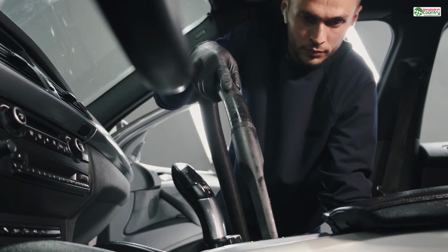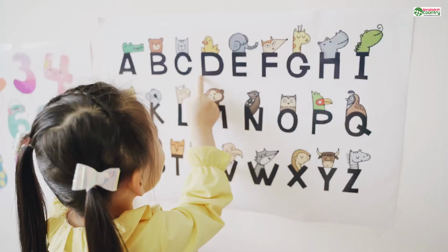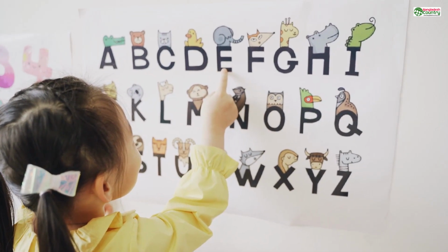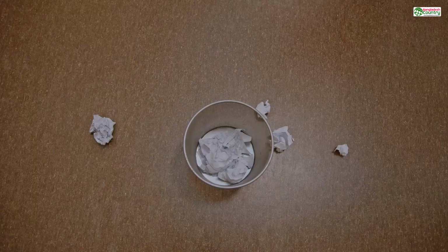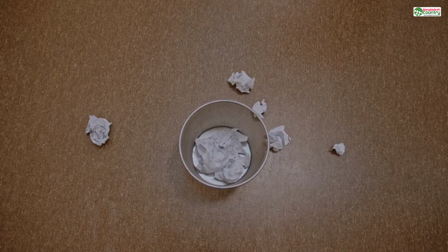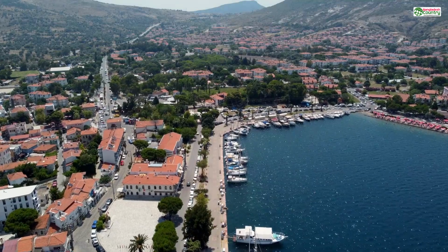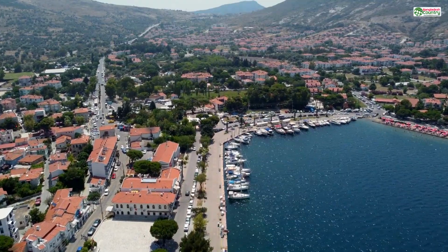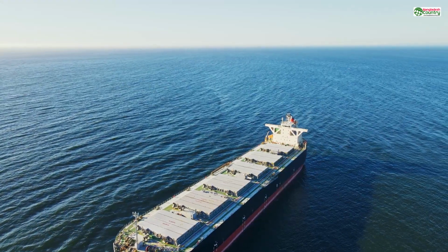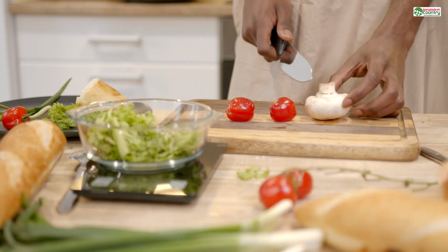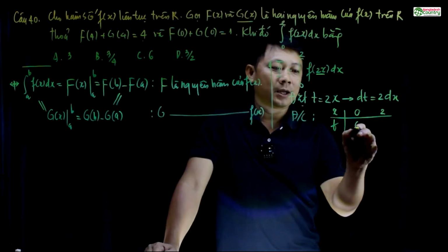By learning these techniques, running the auto repair, analyzing the results, and then manually fixing the holes, flipping the normals, and deleting the internal junk, you transform your model. It goes from being a fragile, leaky suggestion of a shape into a perfectly sealed, unambiguous, solid object. It is now a watertight vessel, ready for the slicer to understand it perfectly. Every single layer will be clear. Every instruction to the printer will be precise. You've closed all the leaks.